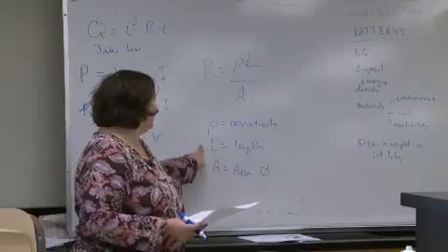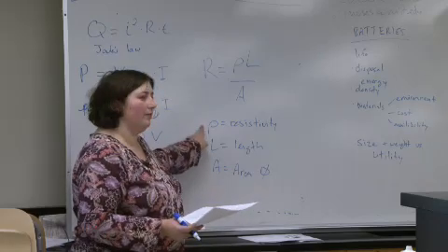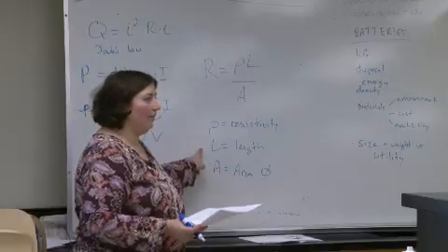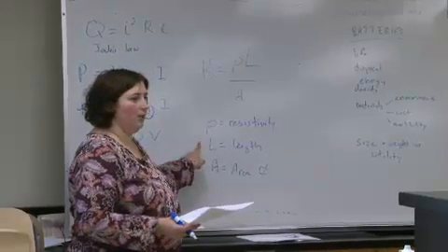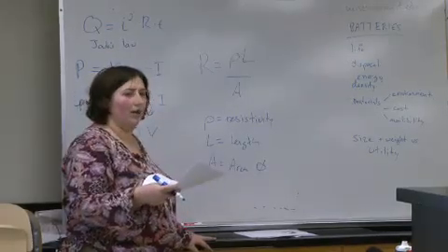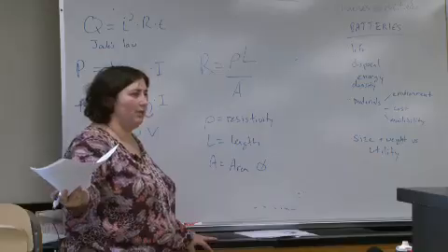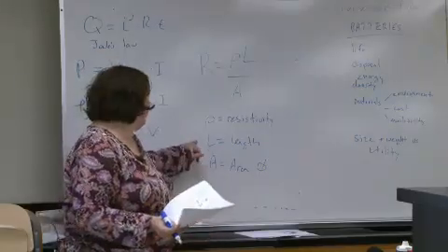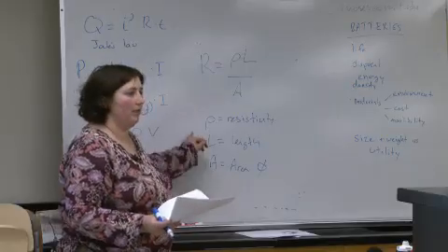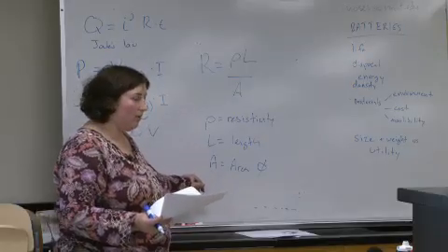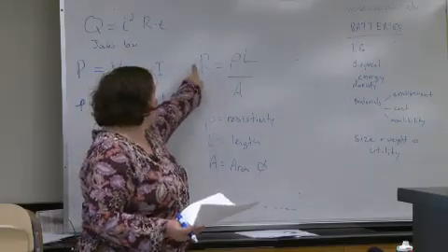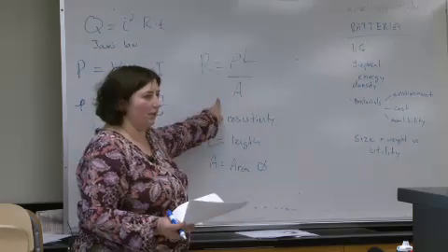So with copper, your resistivity is probably going to be basically fixed based on your costs. Length is something you can control, but is also a bummer, right? Because if you want to power a house that's an extra few blocks down, you can't if you're limited by your length. And then your area, your diameter, again, is going to be completely related to cost. From a cost standpoint, you want a really small area, but to minimize your resistance, you want a really large area.